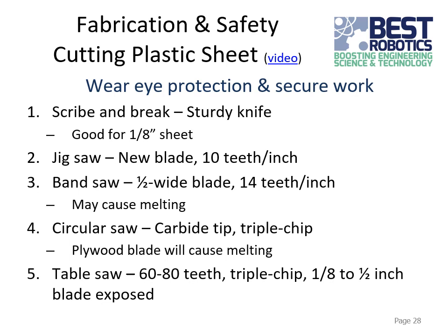Plastic especially can chip or melt and have little melty bits of plastic fly out while you're cutting it. You don't want that in your eyes. So always wear eye protection when you're cutting things or working with power tools. And also make sure that you're securing your work. Don't try to cut something while it's loose and flopping around. Clamp it down to a sturdy surface, or put it in a vise, something to hold it steady.